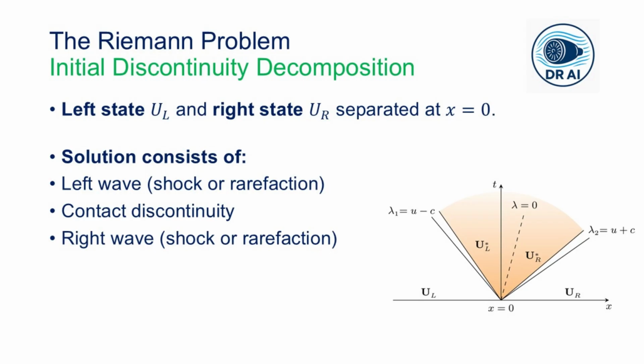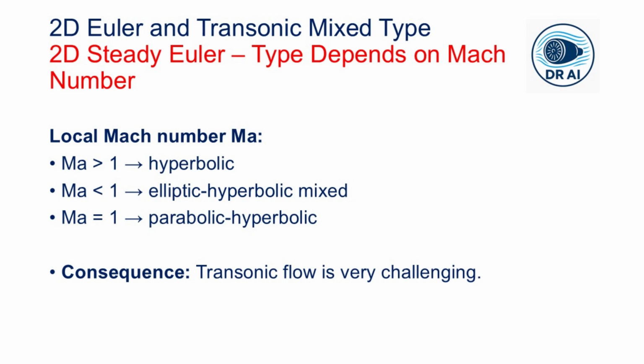Downstream pressure cannot propagate upstream. In a subsonic region, we have one eigenvalue negative, which means that upstream influence exists. That is why a subsonic nozzle design must consider downstream back pressure.